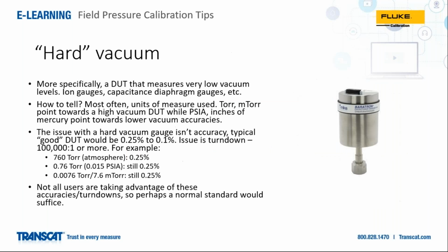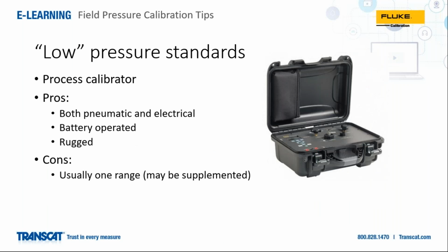The first question we have is regarding the calibrator that was shown in the case. Does that supply pressure, or is an external source needed? It supplies its own pressure. This calibrator has a 300 psi battery powered pump in it. It's also vacuum capable. It's hard to see in this picture, but this calibrator also has inputs for connecting an external pressure source. So if you have a compressed air supply and you don't want to run the battery down, you can run an external gas supply into this calibrator. So it's both a pump and an external supply.